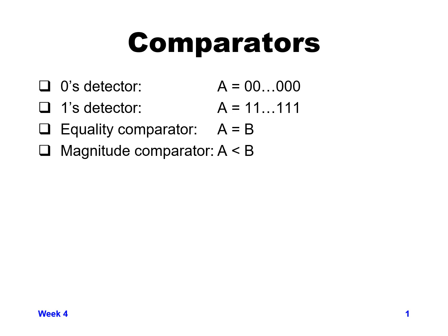So two of the easiest, or not necessarily the easiest logically to think about, is a 0 detector or a 1 detector. A lot of times there are certain functions where it's useful to know, is the value that I have all bits zeros. So instead of taking A and B and trying to compare them to each other, you take one of those values, either A or B, and say, is the value of A all bits equal to 0? So that's a 0 detector.